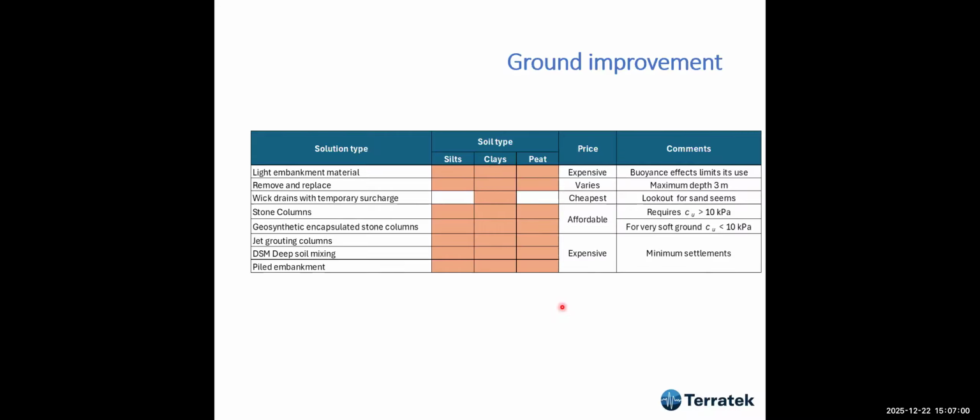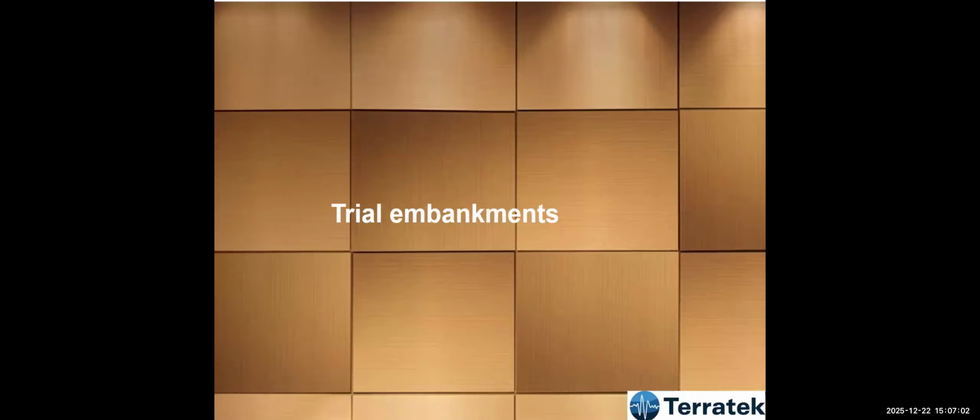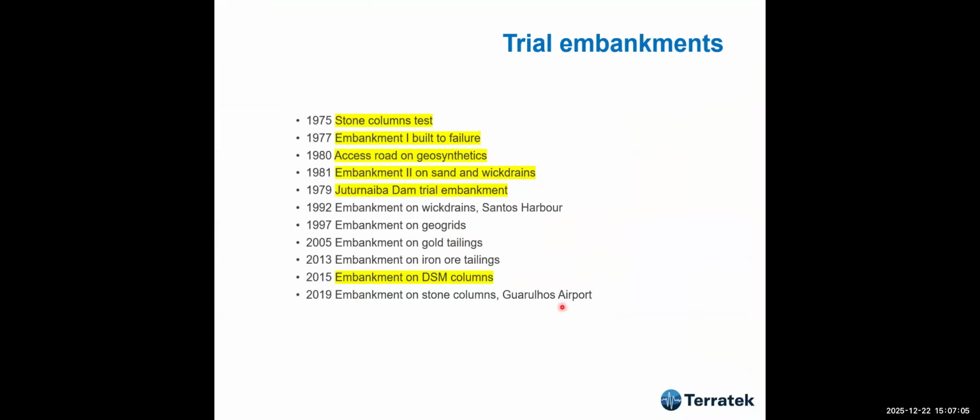If you have time, you use wick drains. If you don't have time, you use the other solutions. And how I learned was by carrying out trial banks. This is still very important today when you have very large projects. At the moment, for instance, I'm having a big project with a company from Texas in Guyana, and we did a lot of trial banks, a lot of trials there in order to decide which would be the best solution.